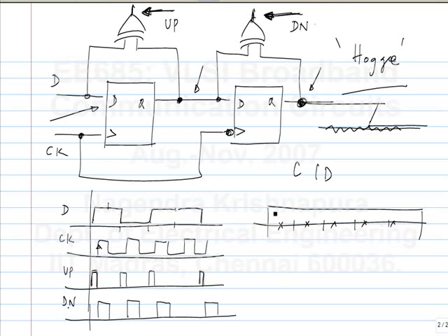So yeah, that's true. If you have a long string of identical digits, you will have a problem, and how long it is depends on the design of the phase lock loop. If the ripple in the control voltage is large, then when you start with the string of identical digits, the clock frequency can be far away from the data rate. In that case, you will accumulate phase error soon. So this is related to what you are asking. It's not reference feedthrough, but this kind of jitter in the clock. If you have too much of that, you cannot tolerate long strings of identical digits.